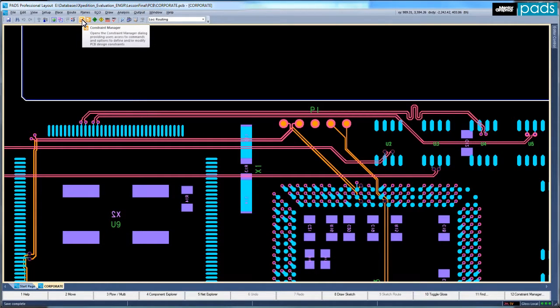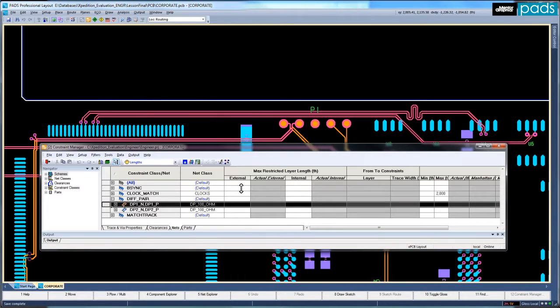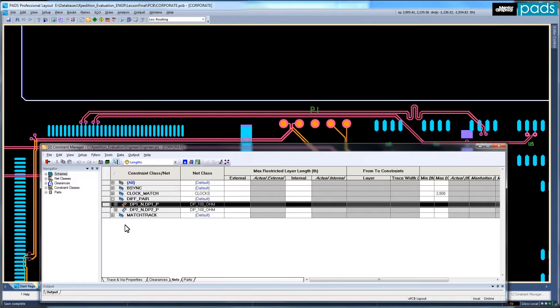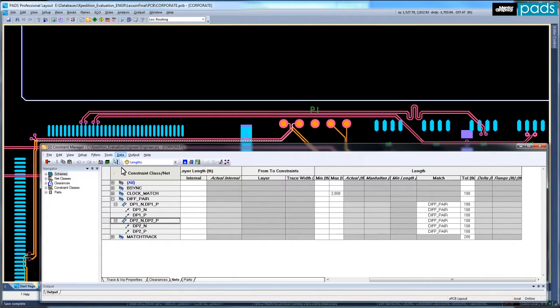Viewing the differential pairs in the Constraints Manager also allows the routed trace lengths to be compared to the rule defined. This is done by loading the Constraint Manager actuals from PCB layout. This is extremely valuable on complex designs where you, the engineer, may need to review the results in order to compromise on the rule to meet 100% connectivity targets.